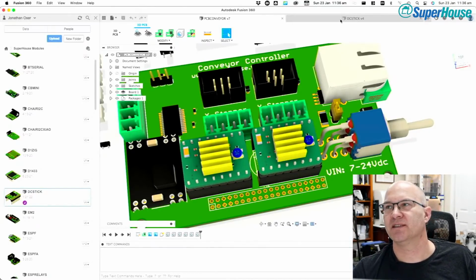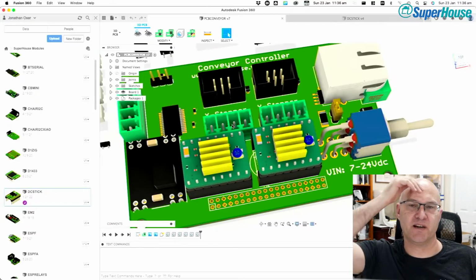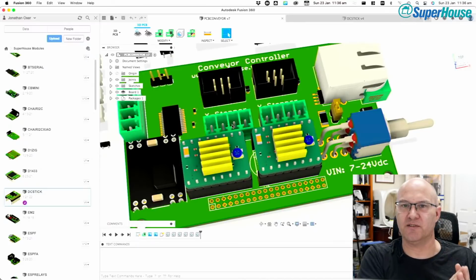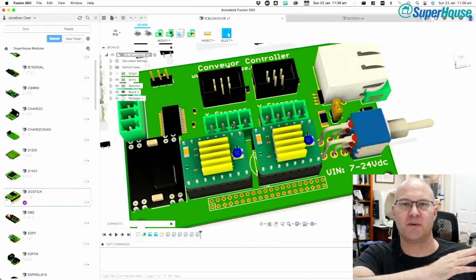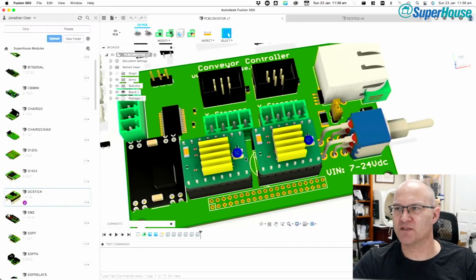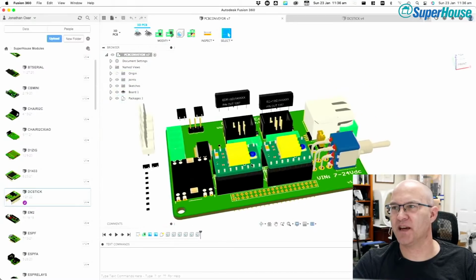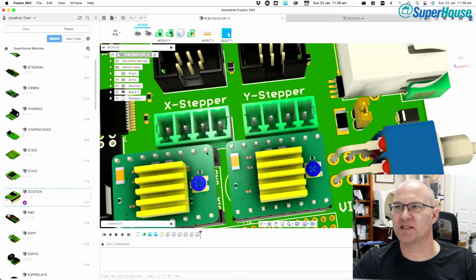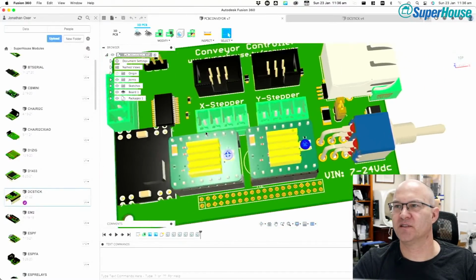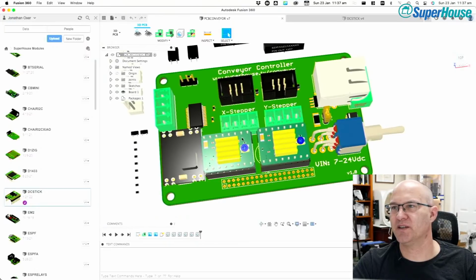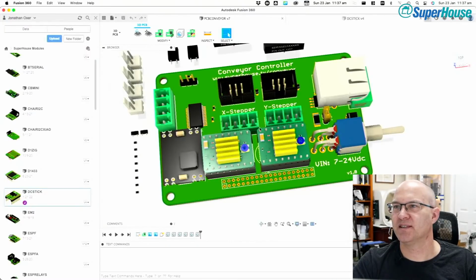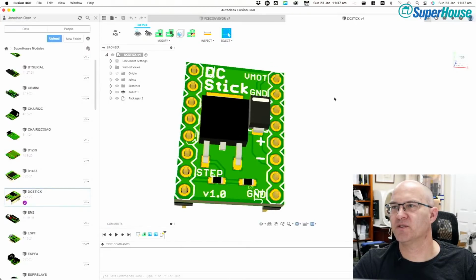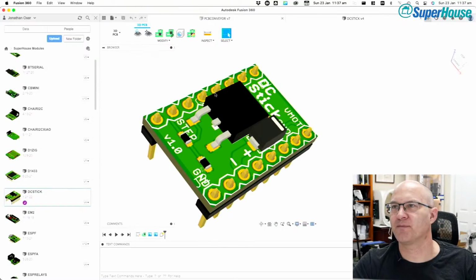So typically, a lot of the time these things use compressed air, and then we want to be able to control an air solenoid to fire something that is air powered. So what that would do is allow us to use this same carrier board and control a stepper motor plus a high power solenoid off the same board. And all we do in the firmware is use the step pin right there to control the output on the load.